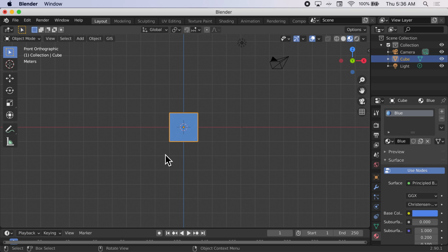How we do that is we're going to press G for grab, and then Z for the direction that we're going to move it, and then by how much. So I should say G for grab, Z for the axis, and then after that you put a number. A positive number will be in the positive direction, and a negative number would be in the negative direction. We're going to move by 1 in the positive direction, so I am about to type G, Z, 1.